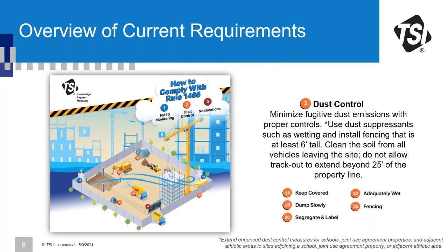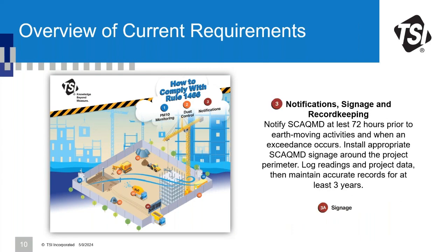as well. So notification, signage, and record keeping. This I see more and more as I travel around the area. You have signs that are very noticeable and legible, indicating where to go if you do see dust leaving a site, and it has a phone number of a project manager there. So there's specific parameters that you have to meet for your signage. And also from there, your record keeping. So logging your records, your readings, maintaining those records for at least 3 years is all part of the rule.